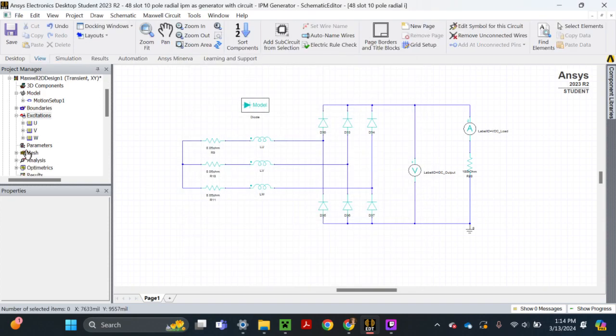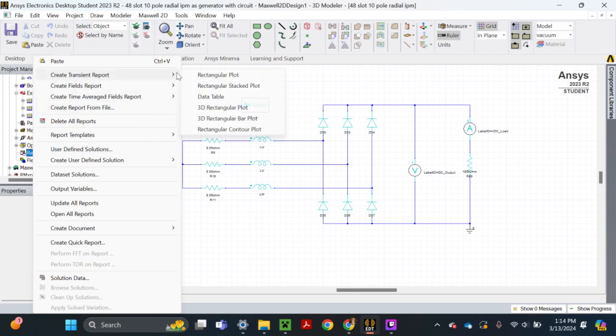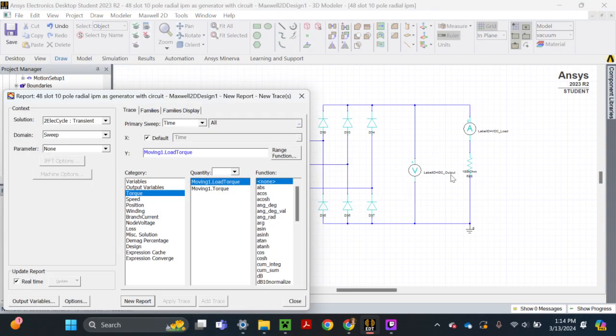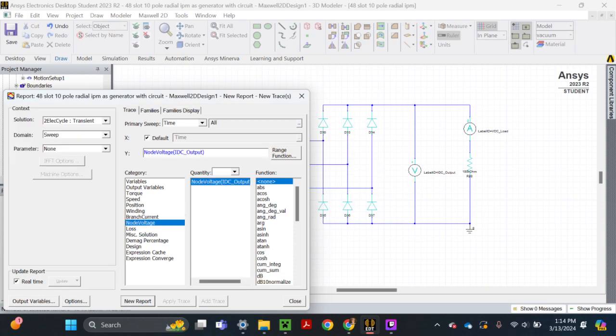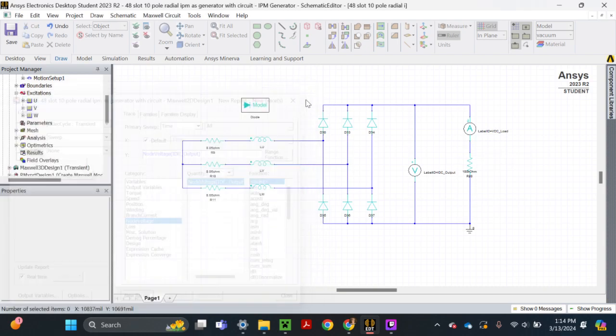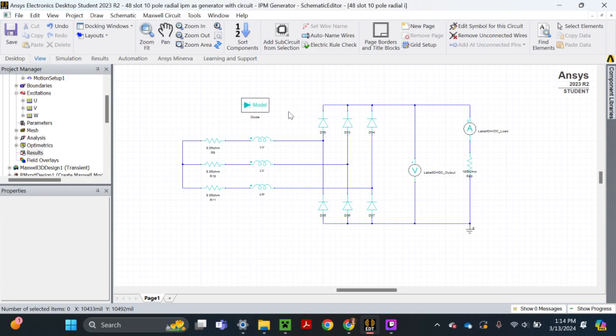And then when you run the simulation, you'll have variables for whatever you have in the circuit. So I put this voltmeter and this ammeter in the circuit, so it'll be in branch current and node voltage is what these will be reading in the transient report. So if you have any more questions or you want to design a specific circuit for your project, you can ask me questions about that and I can help you guys right now. But besides that, I'm just going to open it back up to office hours / project time.